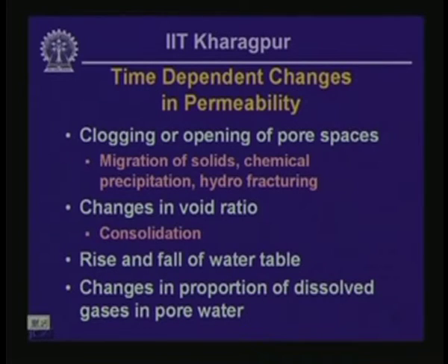Fourth point is changes in proportion of dissolved gases in pore water that also might actually lead to a time dependent change in permeability, because dissolved gases tend to alter the viscosity property of the pore fluid. As a result, permeability changes depending on the amount of dissolved gases in pore water.